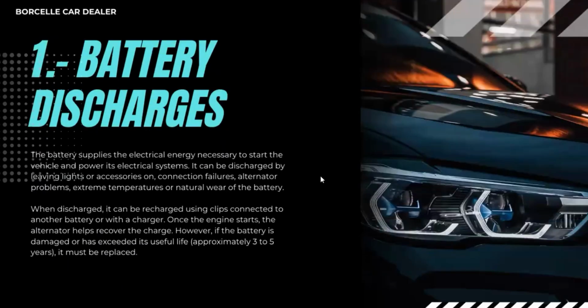1. Battery discharges. The battery supplies the electrical energy necessary to start the vehicle and power its electrical system. It can be discharged by leaving lights or accessories on, connection failure, alternator problems, extreme temperature, or natural wear of the battery. When discharged, it can be jump-started using clips connected to another battery, or charged once the engine starts. The alternator helps recover the charge.